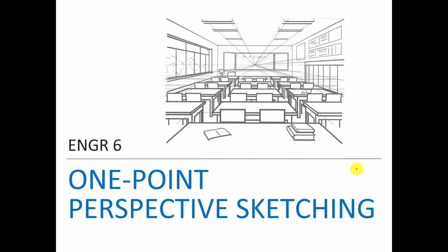So when do we use 1-point perspective sketching? It's when you have a certain plane that you're looking at, and that plane is important. The other sides are not that important; they're like lateral sides of the object. Just the frontal surface is important. Like you have a building, and on the facade, its frontal surface has more features on it, and you want to emphasize that, and not the side. The side is just the walls. That's the case where you want to use a 1-point perspective.